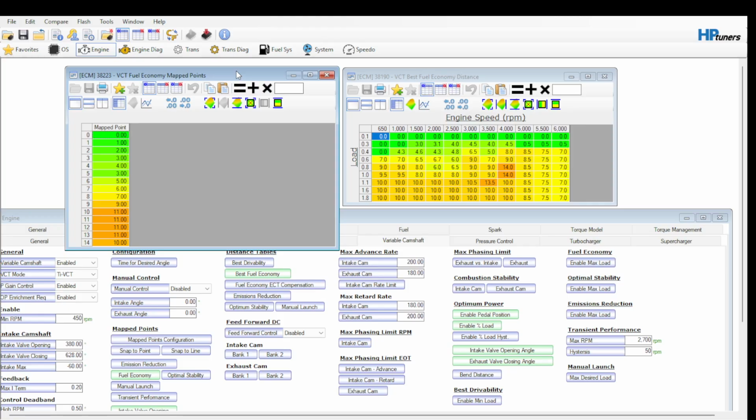What they're doing is basically allowing the timing chain to rotate 60 degrees in advance on the intake side of the camshaft. So the crankshaft still turns at the same rate if everything else is constant. But now, because the oil pressure has filled those lobes and maxed out the advance on the intake cam, it has maxed out the valve timing on your intake cams, right? And your intake and exhaust cams can advance and retard accordingly. I think the exhaust cam gets up to like 50 degrees, but that's nuanced stuff.